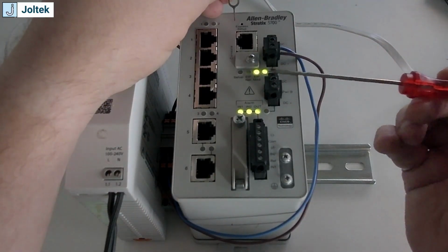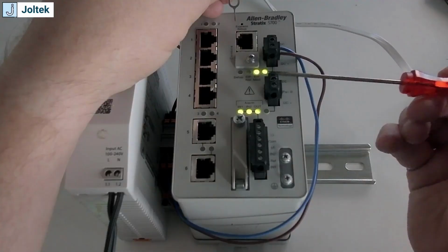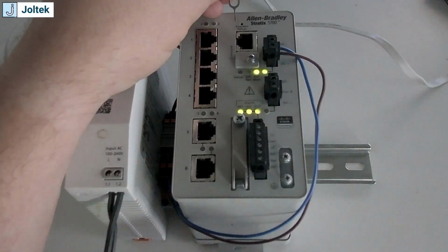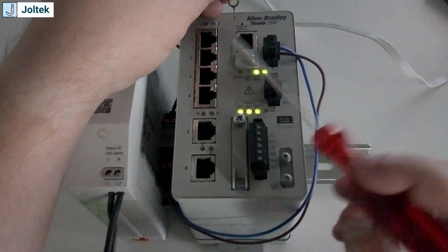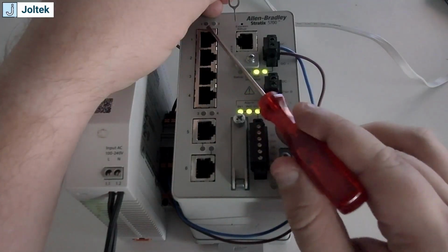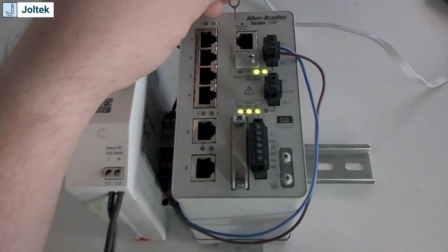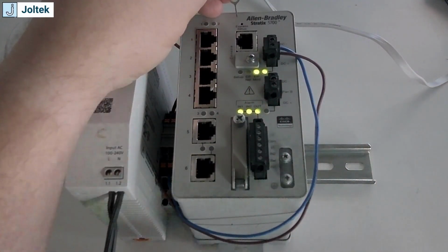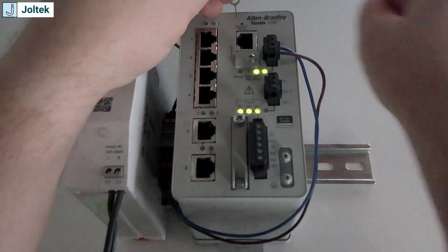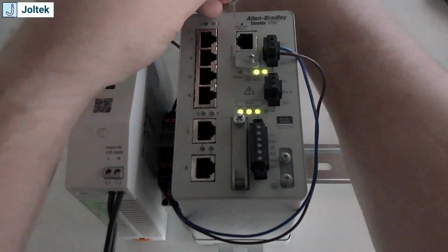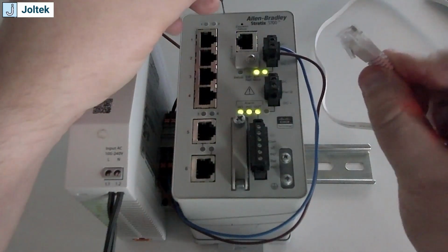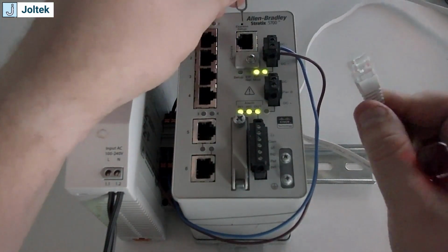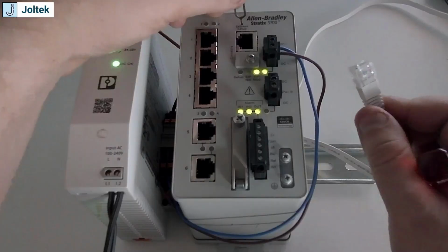But what's important to pay attention to is the lights. We only have a couple of seconds before we release. So we are expecting the lights to flash green, but we're also, after we release, expecting the first port, since it is available, to start flashing green so that we could connect our adapter on the Ethernet side into the port and assign a DHCP address. So once again, it's just a standard jack that we have here. Let's go through the procedure.